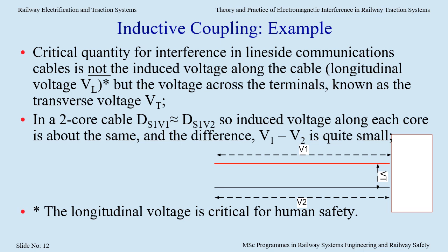Note that the longitudinal voltage is important for human safety, electrical shock hazard, and it limits the maximum length of continuous line-side cable.